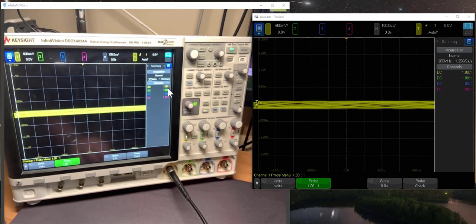The next thing that we're going to adjust is the scales, the vertical and the horizontal scales. Now when we pushed Default Setup, it gave us nice whole numbers for those scales, with the center at 0 for voltage and the center of the screen where that caret is. That's where we're adjusting the t equals 0. That's where we're triggering the signal at, also at 0. For me personally, I think it's really important to have whole numbers on the axes. That way I can immediately read what the values are off the screen.